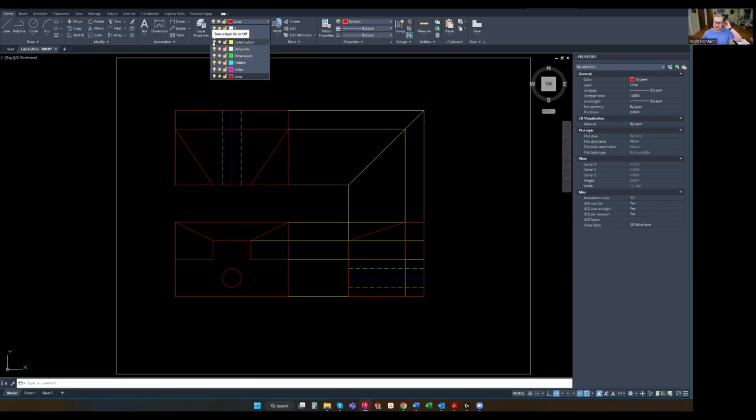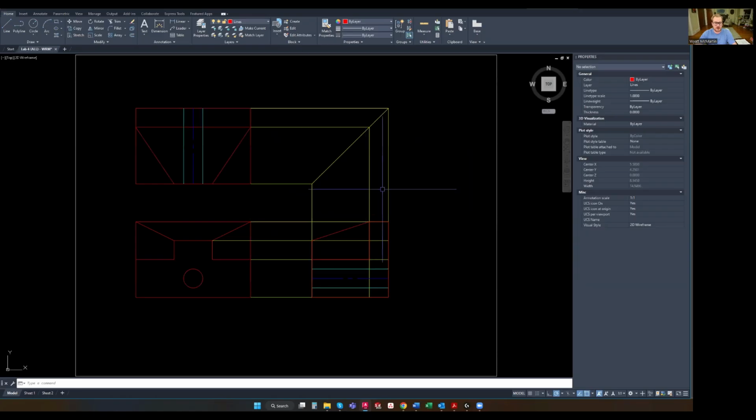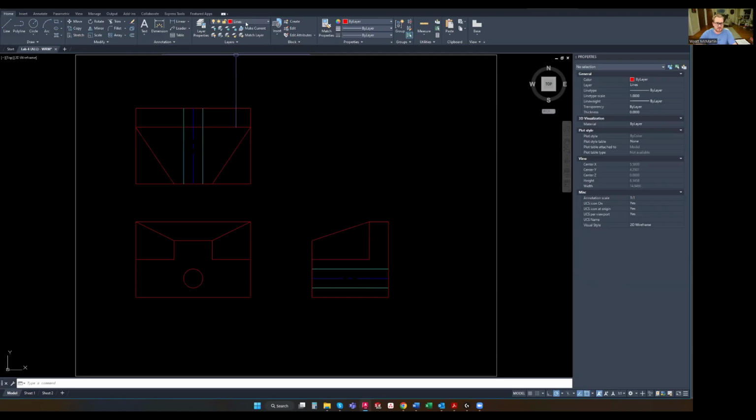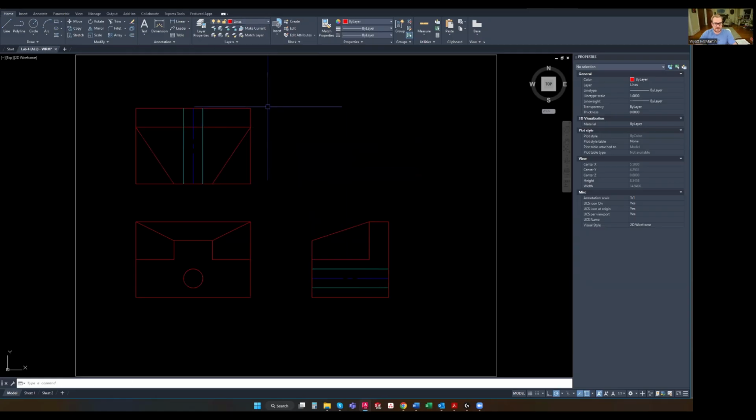And if you're looking at site plans, you could be talking about multiple square miles inside model space. So, we're using an 8.5 by 11 sheet of paper, but this is an infinite space here. So turning off a layer in that case makes a lot more sense because you're saving computer memory. For our cases, we could just go ahead and freeze it. And that way, if you ever want to reference, oh, hey, let me look at my construction lines, there they are. This is also good.